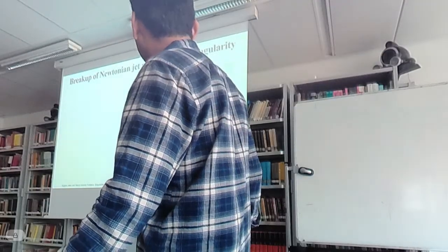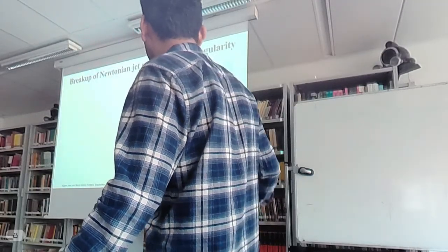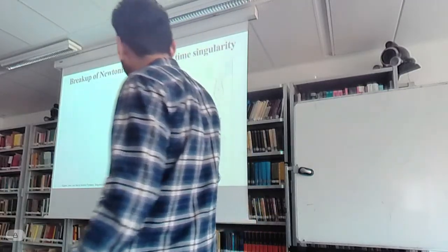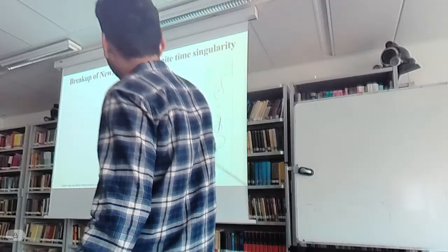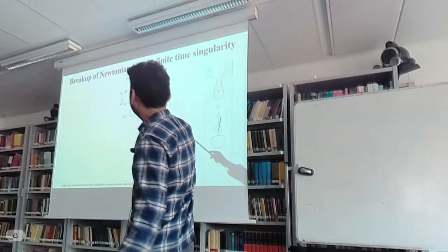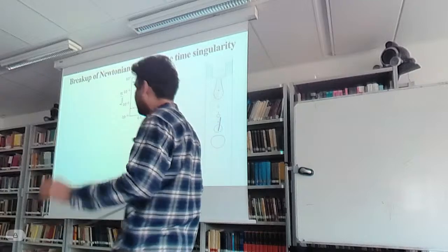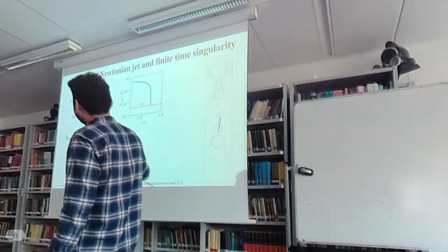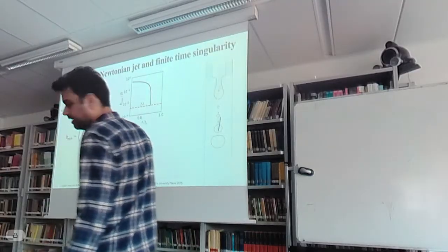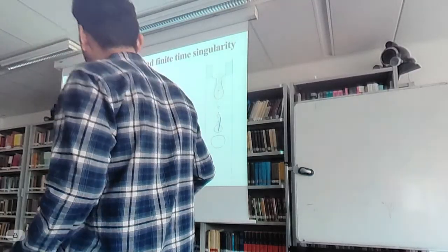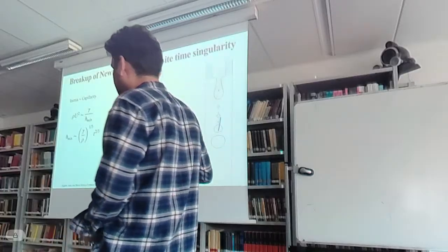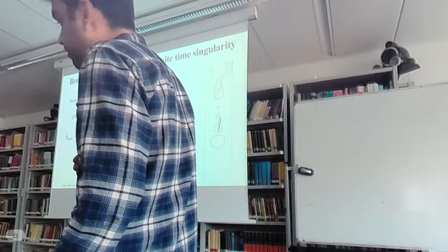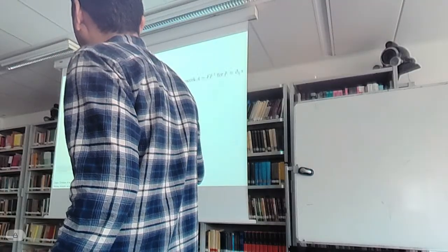So again, we start with the Newtonian case, and I look at the secondary breakup here. I track the height of the interface as a function of time, and we see that it breaks as we approach this delta H, which is 1 grid size. And you can get this scaling by comparing inertia and capillarity, that it goes like T to the power 2/3 to the singularity that breaks it. But when you have elastic stresses, you need to consider them.